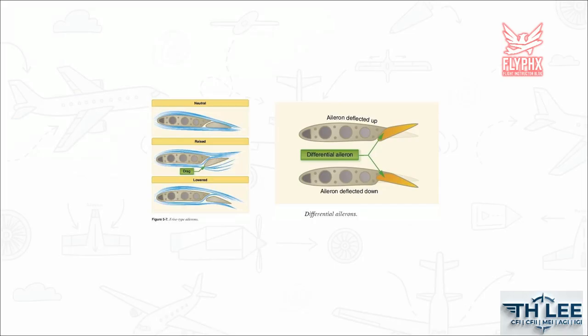Aircraft manufacturers know adverse yaw is a huge headache, so they've engineered some pretty clever fixes. First, consider differential ailerons, which are super common on Piper Arrows and Cessnas. The upward aileron simply travels further up than the downward one travels down, creating balancing parasite drag.